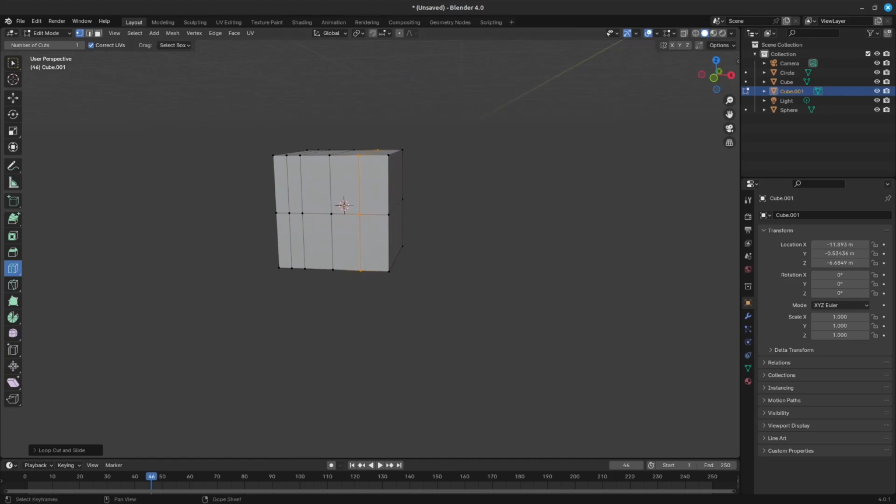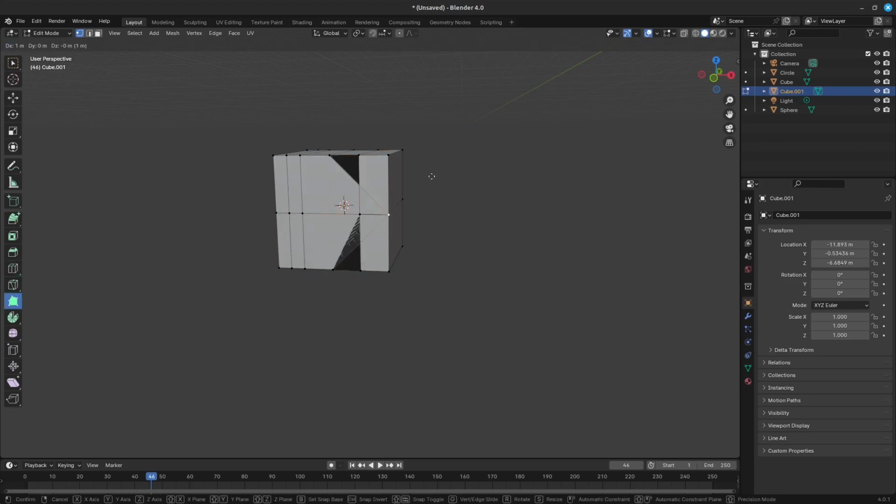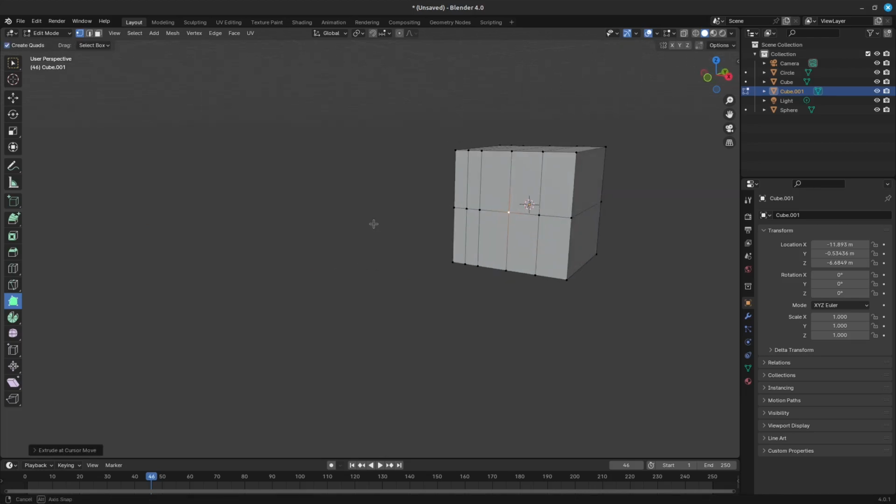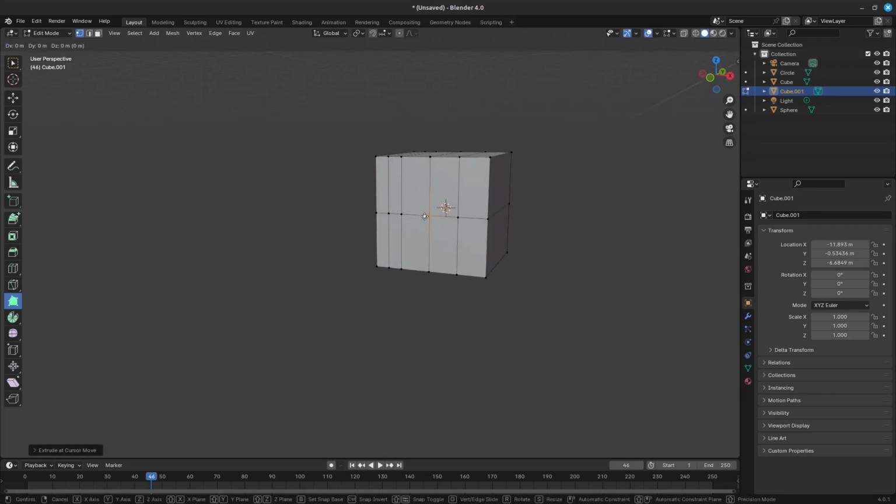When creating a face, the face can be previewed by holding Ctrl. You can delete mesh elements with Shift plus the left mouse button. To move vertices around, use the left mouse button. When moving them around, you can extrude edges too. Edges can be extruded by moving the cursor close to an edge and using the hotkey to extrude the edge to the desired location. The edge you are trying to extrude will be highlighted in blue while hovering over it.